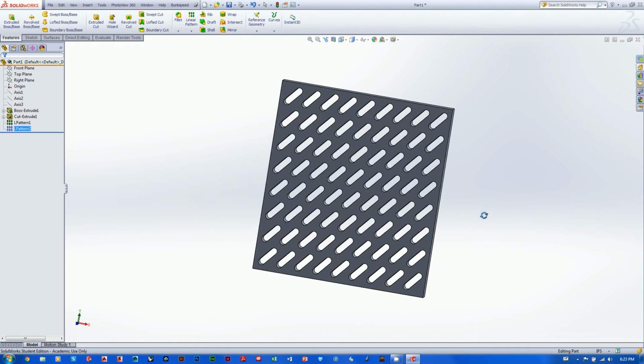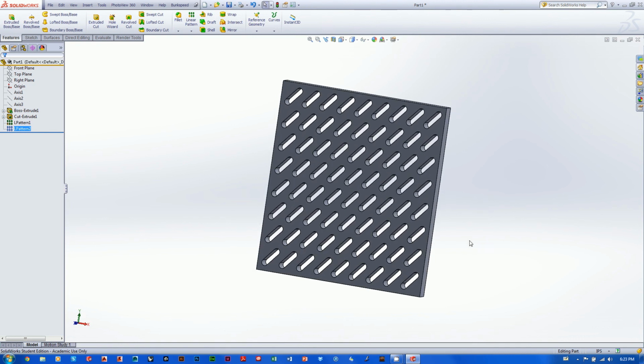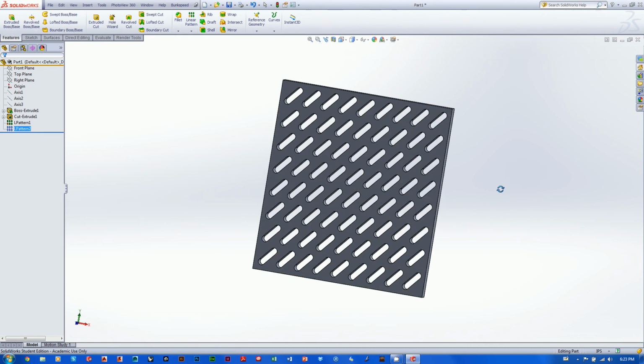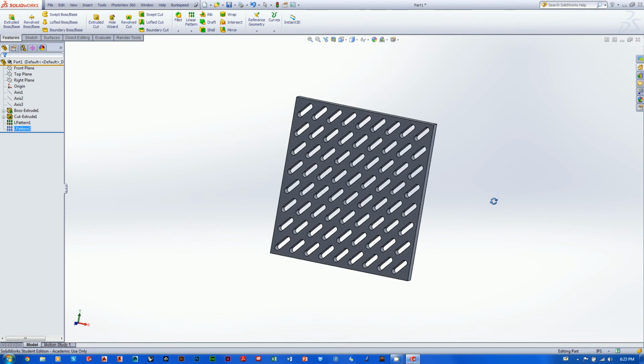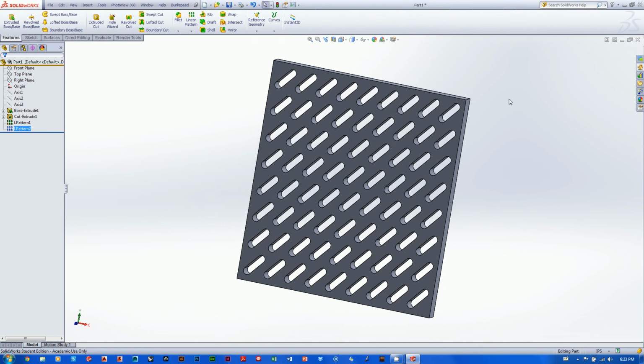So now with the stock tutorials that SolidWorks provides, they would just make super boring little squares and make kind of like a checkerboard thing here. I've used the slot at an angle because it looks a little bit cooler. Hopefully you think so. But this is the drill, right? This is how to do linear patterns in SolidWorks, okay?